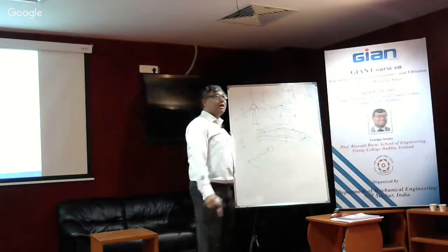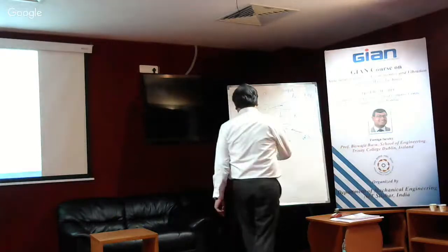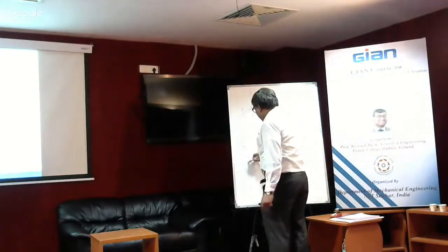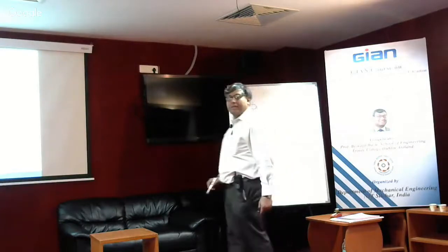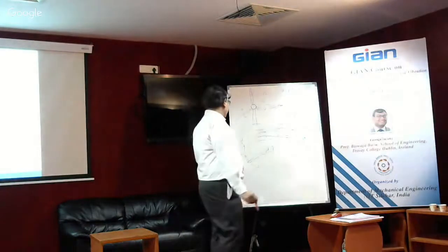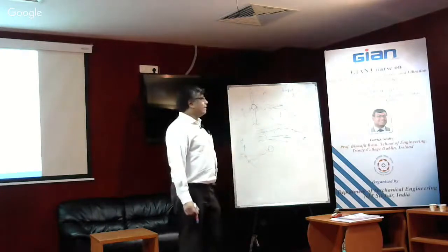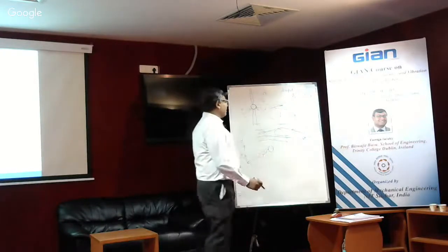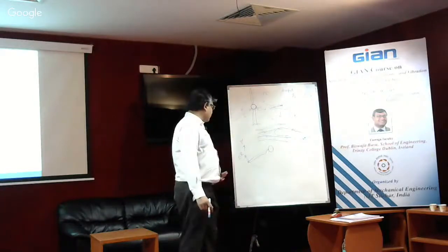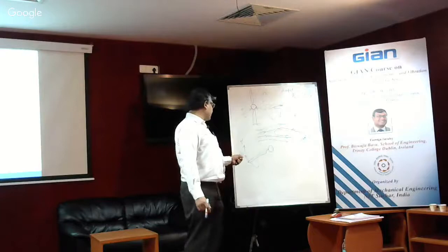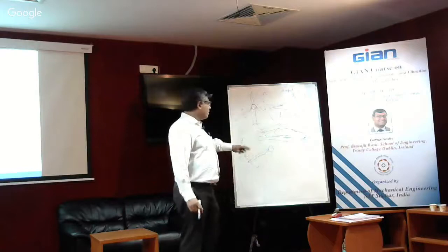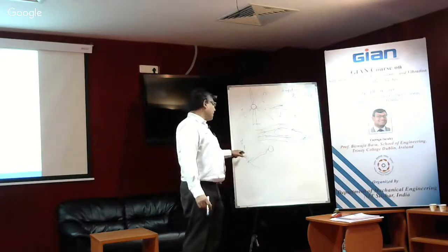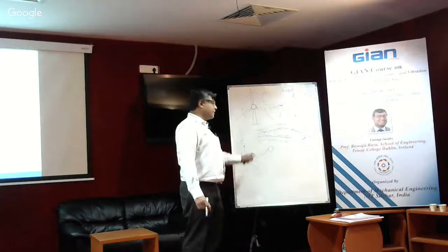So if the radius is r, then effectively you have a velocity of omega times r, right? If you take a cross section at the tip, like I have there, there are two velocities. One is the velocity of the wind, and the other is the velocity of the rotation due to the blade. There's a relative velocity as a combination of the two as well, but there's a velocity which is omega r, and then there is a velocity at which the wind is hitting this.